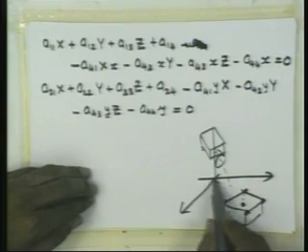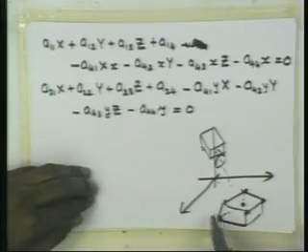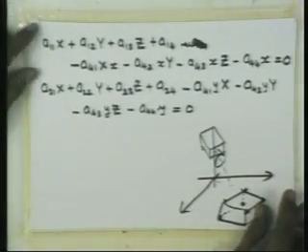I can also know the location of this whole box with respect to the global coordinate frame. So knowing this, I basically know x, y, z of 6 of these coordinates. I have 12 unknowns, I have 2 equations here. So if I write these equations corresponding to 6 points, then I will be able to solve for the unknown coefficients. So this is typically the way the calibration would be done.